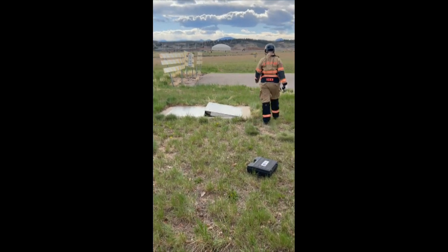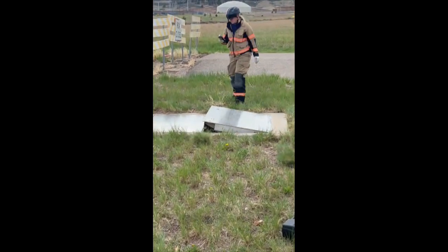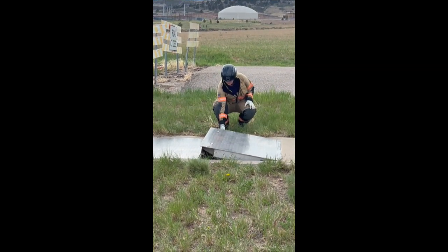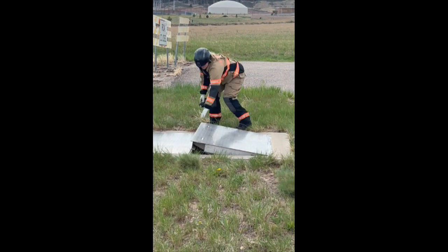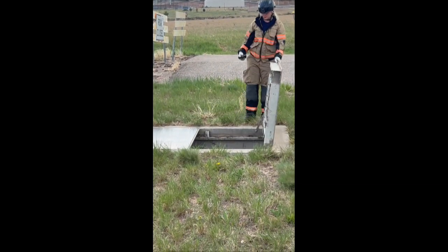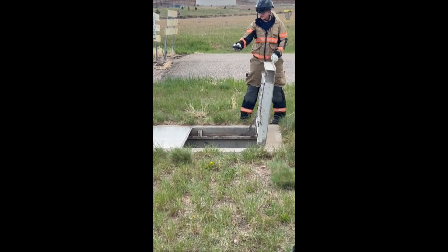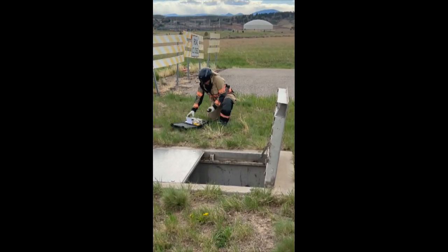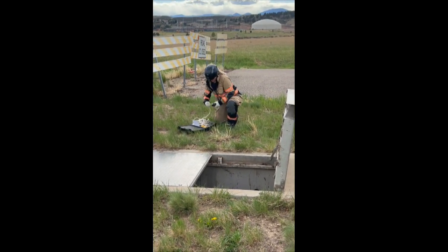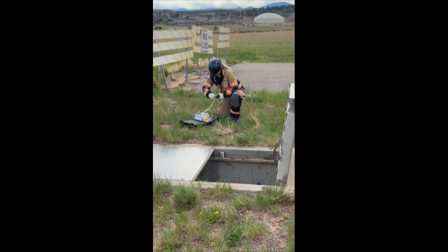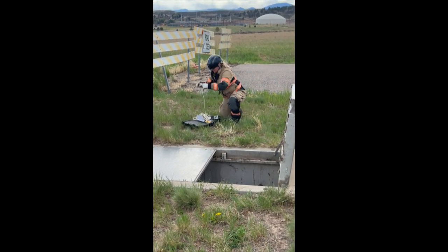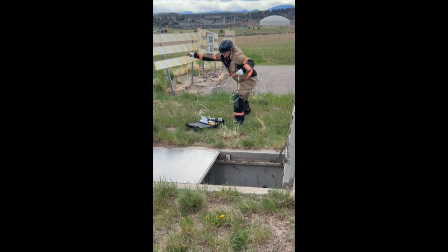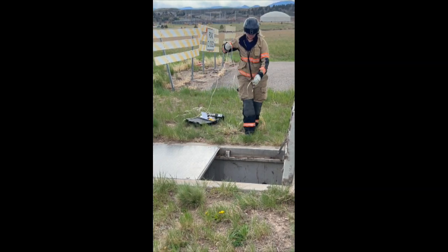You arrive on scene, we want to begin air monitoring as soon as possible. A basic rule using all monitors is to take your first sample from a small opening before opening up the space and to stand upwind of the location. Many times the mouth of the space is already open. Still remember that high concentrations of toxins and flammable gases can accumulate under covers and around openings, and depending on the circumstances, consider wearing an air pack. We want to start and continue monitoring early to create baselines and identify changes or trends of the environment within the space.